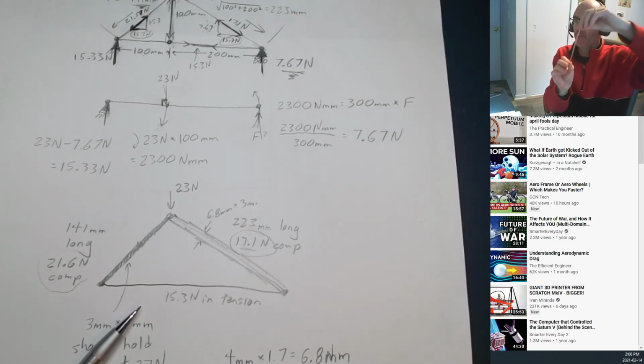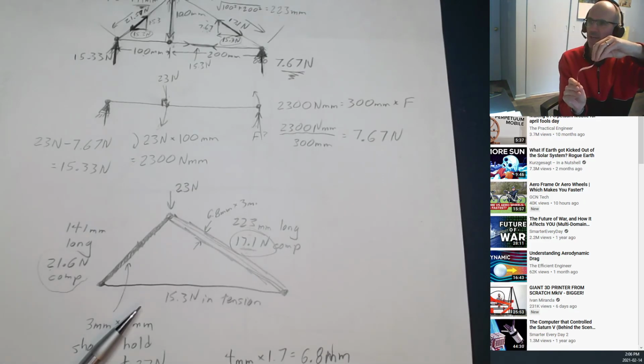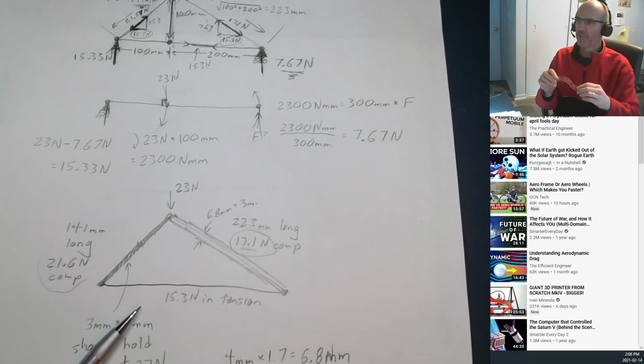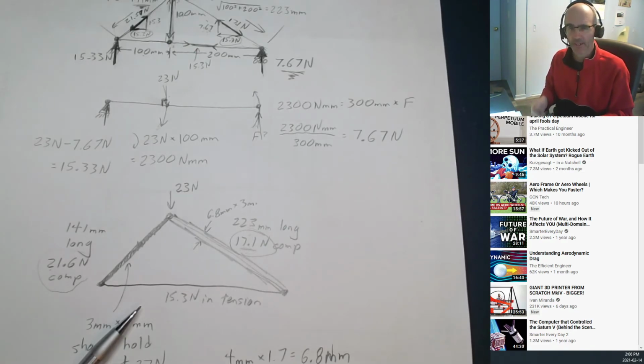And it can do a couple of different modes of failure. It can do a mode of failure like this. So if it's pinned at each end, it'll go into a nice C shape. If it's fixed at both ends, you can see how it kind of goes straight and then it buckles out. Sometimes you'll also get it so that it buckles out in an S shape like this. So you've got a couple of different ways that it can fail with fixed ends. But just take a flexible piece of plastic or something like that and just play with it. You'll see how that buckles and how it fails. And we've got formulas that can explain that.